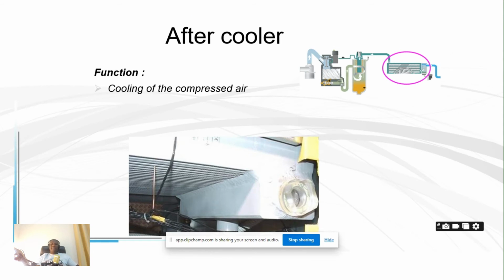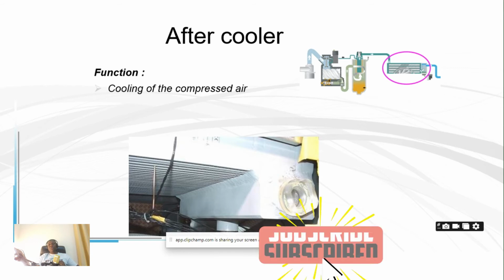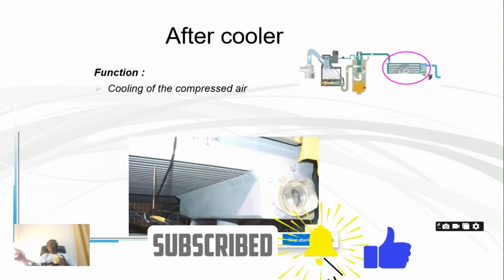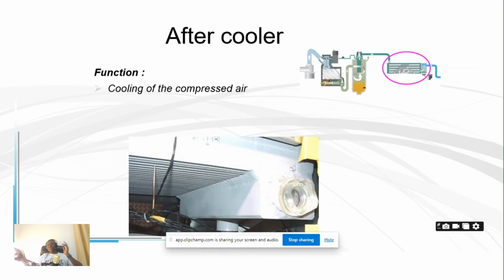Well, this is the aftercooler. The aftercooler is to cool the hot air before it is sent to your system. When a compressor compresses, the hot air, if you don't cool it, can continue to rise, right? An oil injected compressor will shut down if it exceeds 120. So around 70, 80, 90, 100, it keeps going for cooling, and it maintains about 75 to 80 degrees Celsius. So basically, this is a heat exchanger. They exchange heat with air being blown by the fan. That's the fan here.